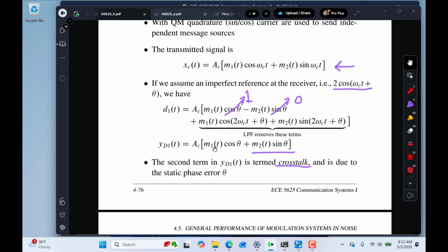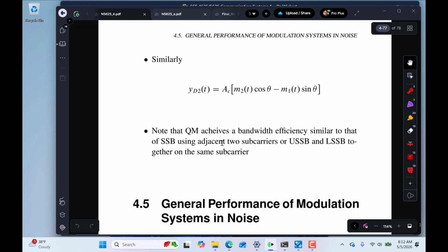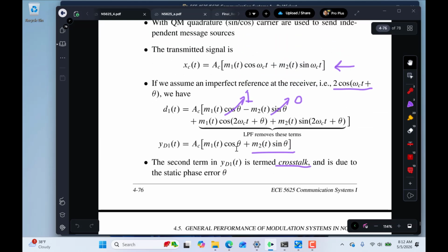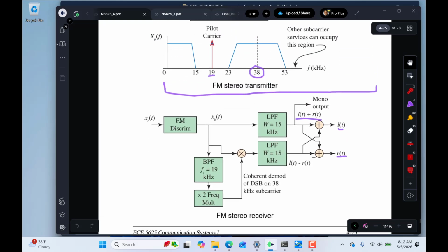And normally they're referred to as the in-phase and quadrature channels, so they'd be made up into a complex waveform at the receiver, but they could be separate analog channels. If you were doing it in purely analog, it would just be two waveforms. So I'll get back into this when I go through the review, but this is a fundamental concept, the so-called quadrature multiplexing. And multiplexing is kind of the theme that was introduced just prior to this.